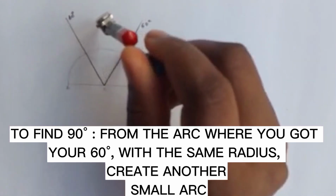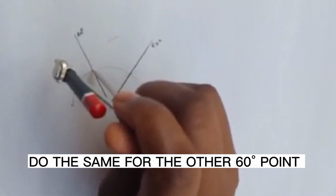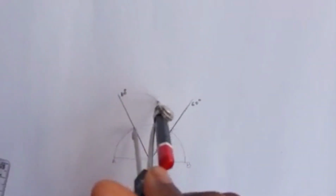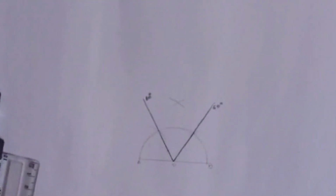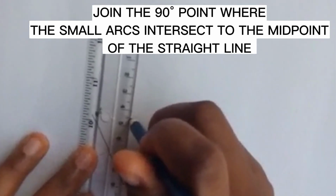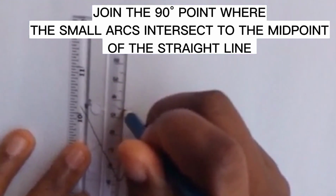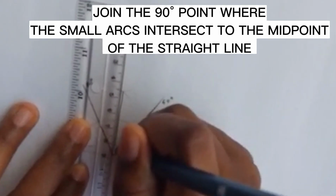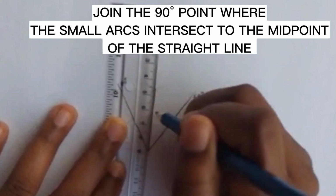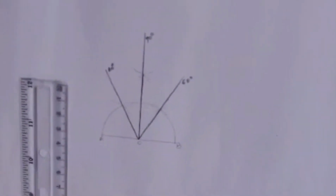Now to find 90 degrees, from the arc where you made your 60 with the same radius, don't change the radius, you create another arc, and do the same for the other 60 degree points. You create another arc. Now you join right from this point where the arcs intersect. You draw a line to the midpoint of the first line that you drew, and this is your 90 degrees angle.